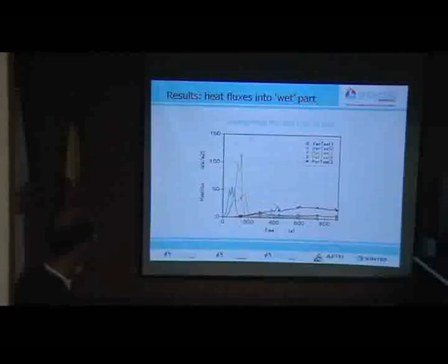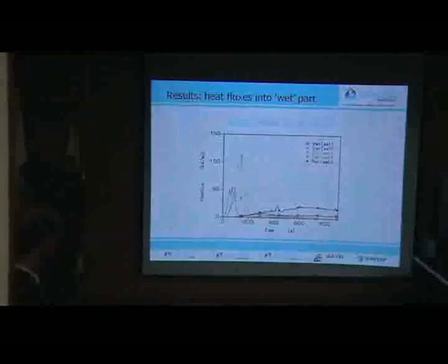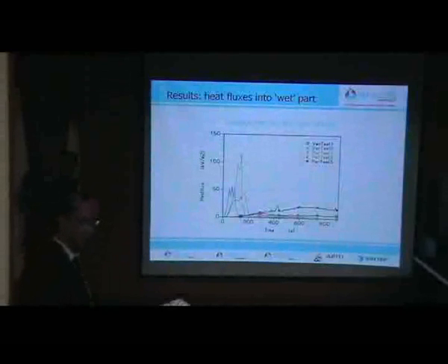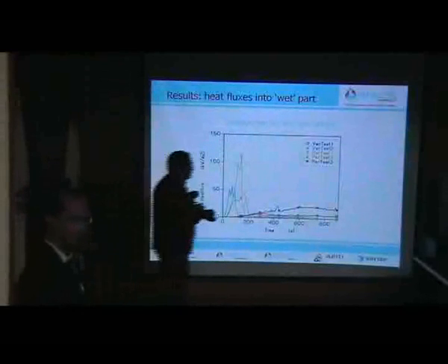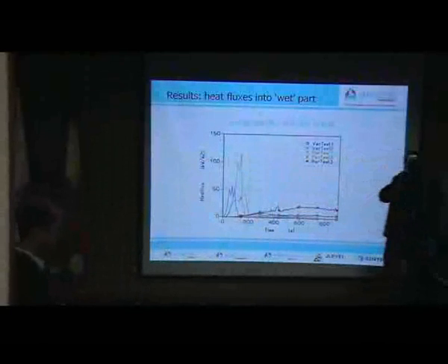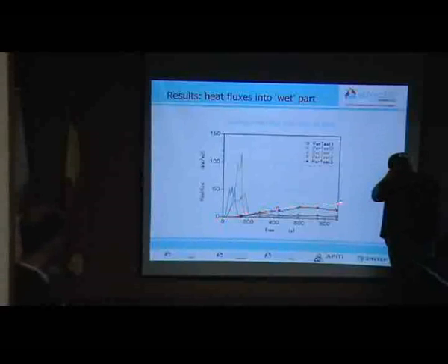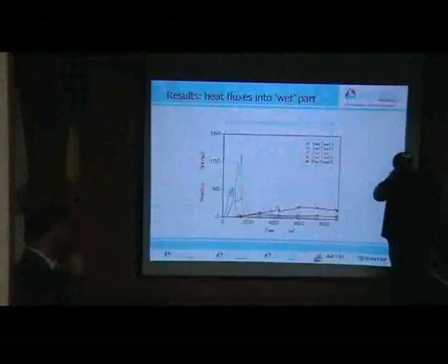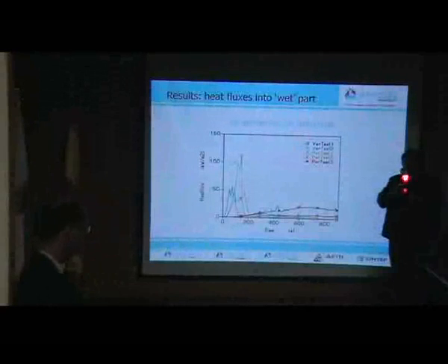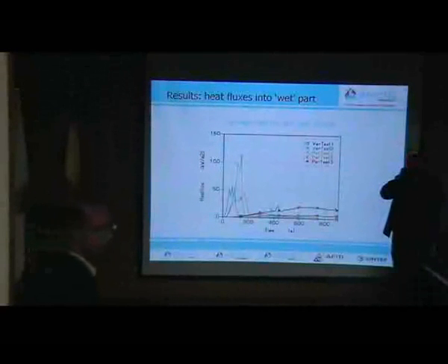This sheet shows the average heat flux into the belly of the tank, into the water. And again, you see that with the pool fires we have the highest heat flux, because the pool fire is situated lower, and the flames go under the tank, because we also have ventilation in the tunnel. When we have a solid fire, the flames are much higher, so they are not so much underneath the tank, but more on the upper part of the tank.